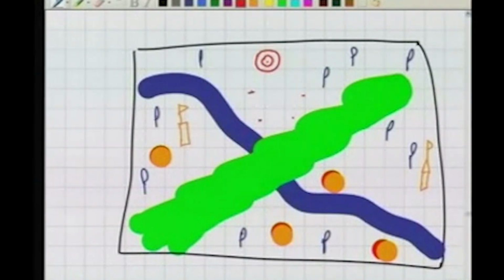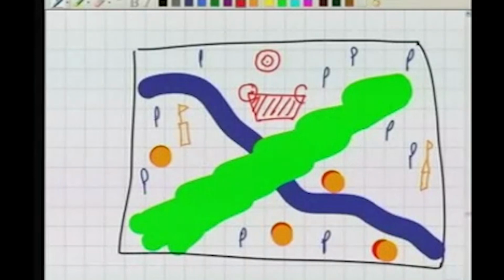How do I locate? The similar way. Wherever I am standing, I am trying to find that location using the back bearing observations or fore bearing observations, converting them to the back bearing to 3 well defined points and locating these individual points. The building is located. Finally, we can also make use of this compass in another interesting thing.